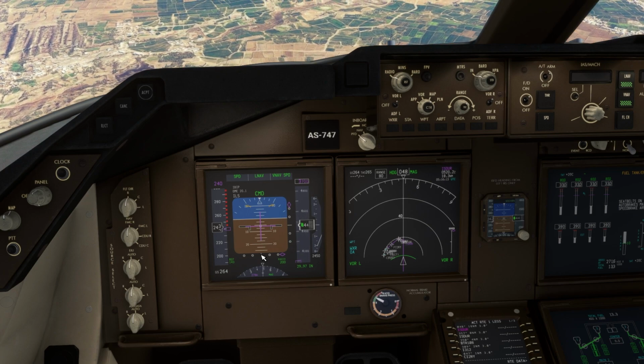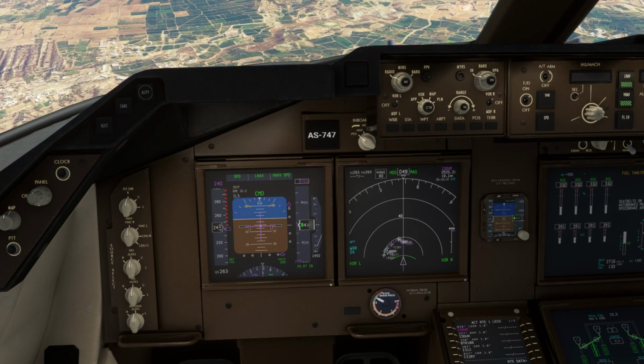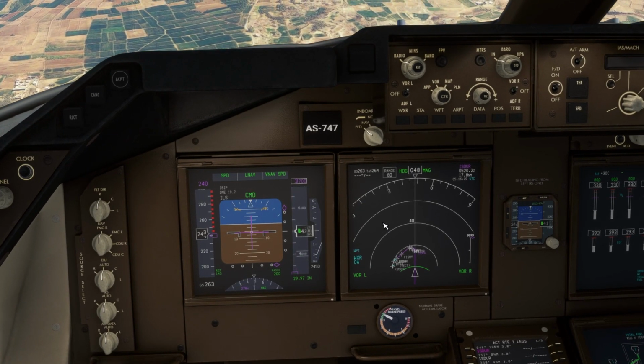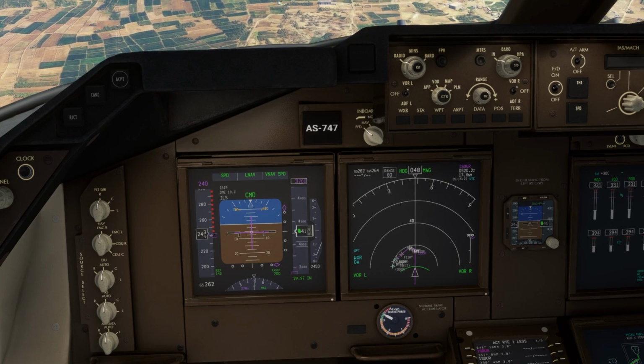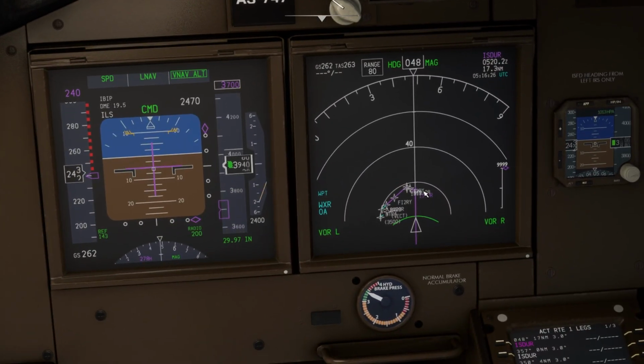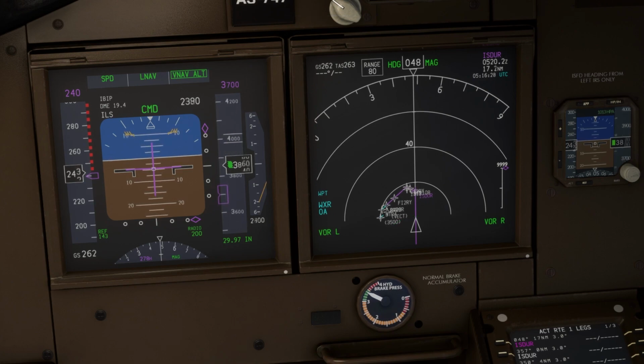So right now this beep which you heard is telling us that only 1,000 feet to go to level off. The descent rate has been high, due to which we are at 3,700 feet, whereas at ISDO I should have been at 6,000 feet, not below this.